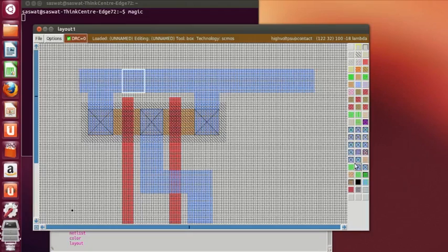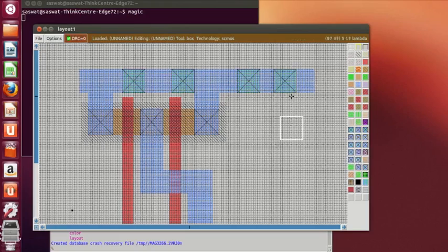So in the commands we were writing NWC, that is N-well contact. Over here we will use N substrate contact. This one, N substrate contact. Now these are too near. Let me undo it.